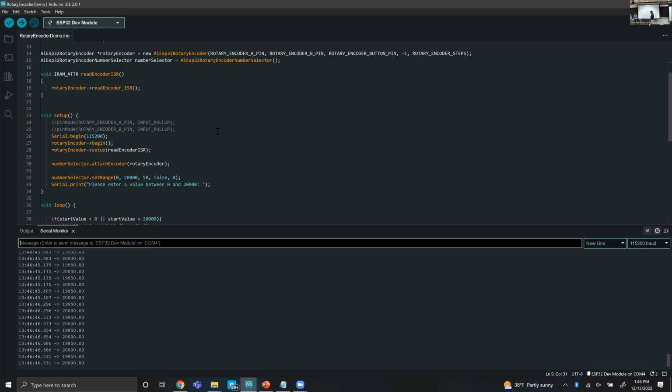Not entirely sure yet. That's a very good question to think about. Now, this is analog, right? That's the problem we have with analog. You have steps, you're limited to the number of steps, basically the rotation. So one way is to make it smaller steps, which you have to see physically what is the capability of this potentiometer. You might find a better potentiometer with higher resolution. And leaving that rate to the user is usually not a good idea.